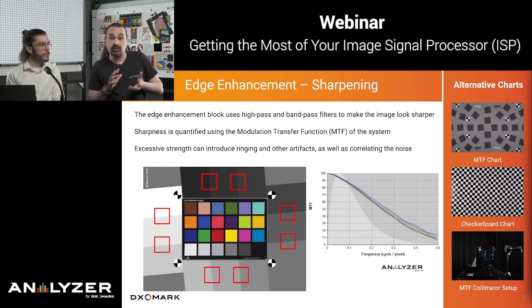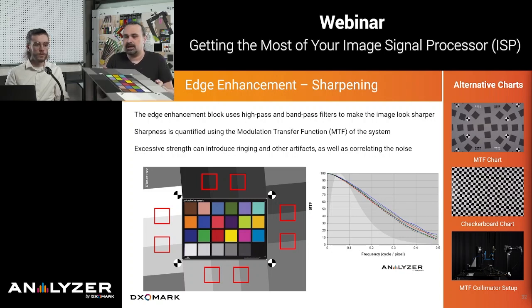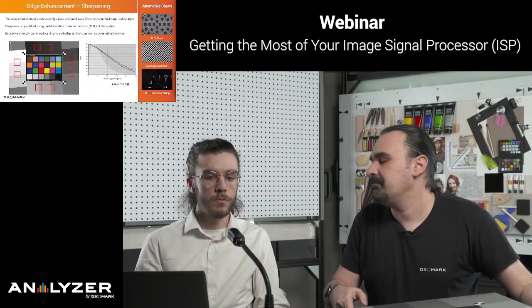It also depends on what your pipeline is going to do. If you have a purely optical system, like a DSLR taking a raw file and measuring the raw file sharpness, whether I take my edge black and white or two different gray levels, the result is going to be the same because the behavior of the system is going to be the same. But if I have something that is a bit dependent on the content because there is a complex pipeline that makes different choices depending on the context, well, low contrast like this one here or our radial MTF target chart may be more appropriate than a black and white target chart.